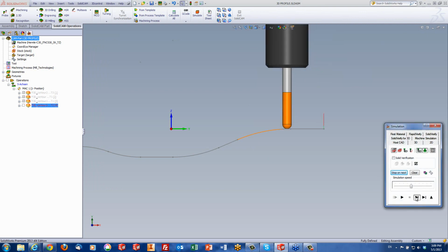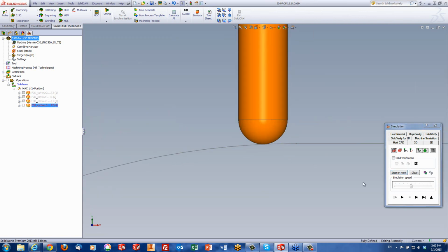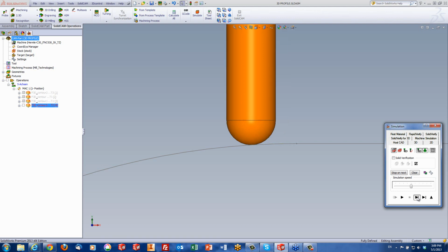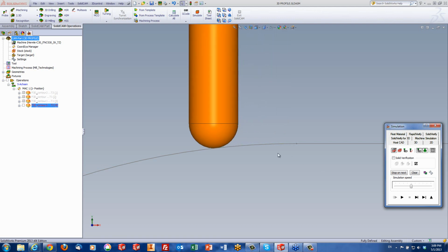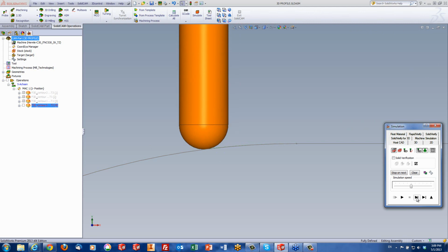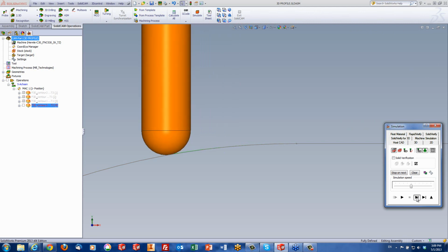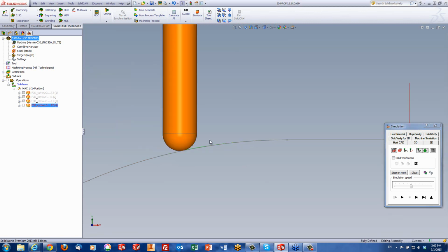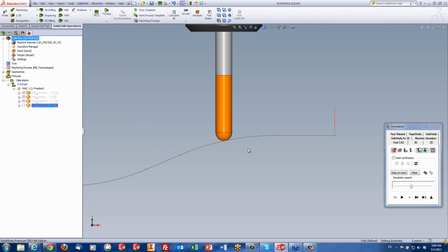You'll see the tool goes in, and right now it looks like the center is touching the geometry, but once it starts going off to the side, you see the center is not touching the actual center over here. It's not touching the geometry itself, the chain itself. Rather, it's moving towards the side. Always make sure the tip is what's touching the geometry itself.